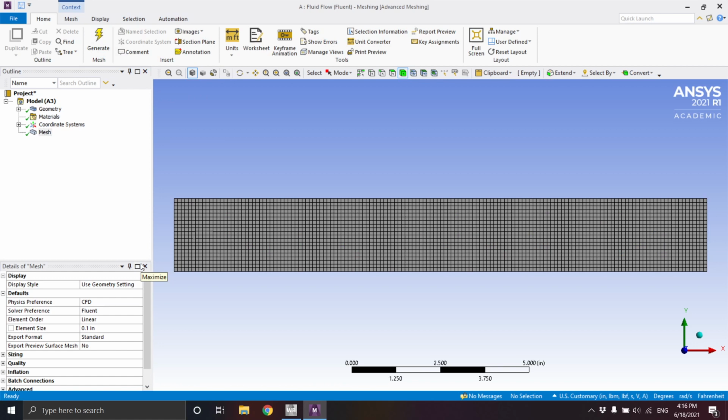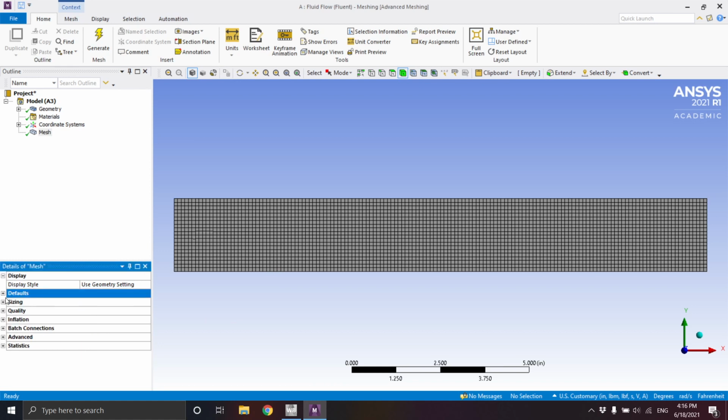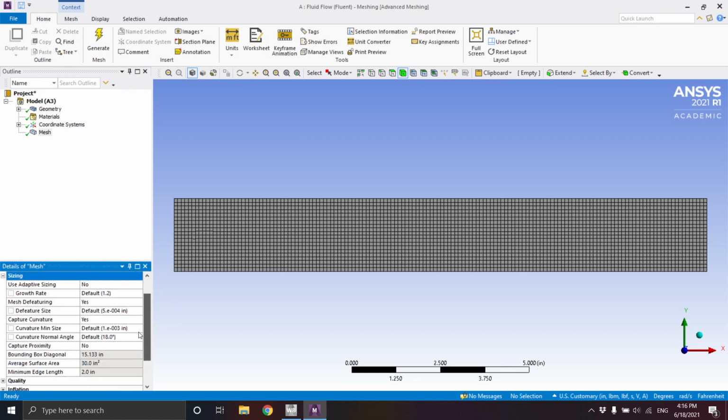As you can tell, it took a little bit longer for us to generate this meshing, but we have very small elements. We'll see later on that sometimes the accuracy from one element to another is going to be almost not noticeable depending on the geometry that we have. So sometimes we want to simplify some problems and reduce our computing time by reducing the number of elements. But for now, this is going to be all in this tutorial.